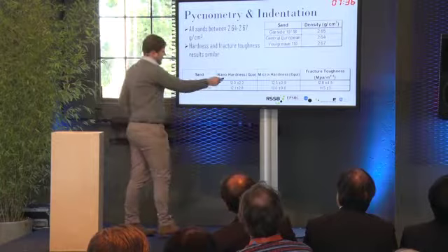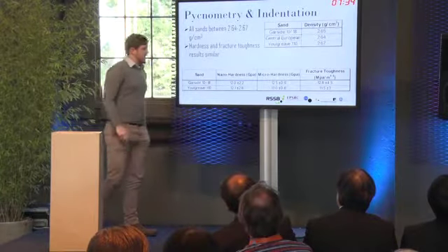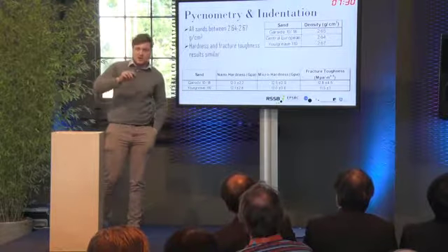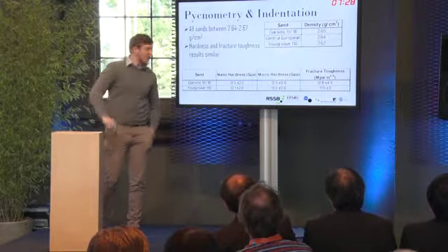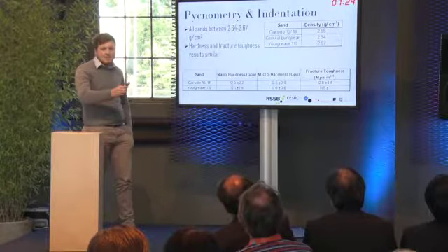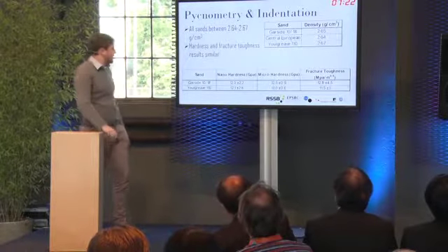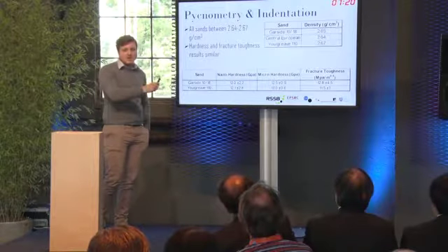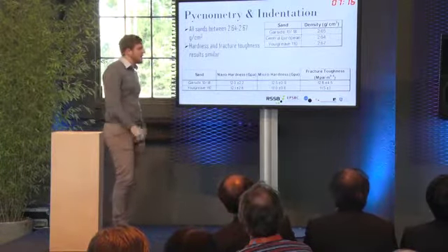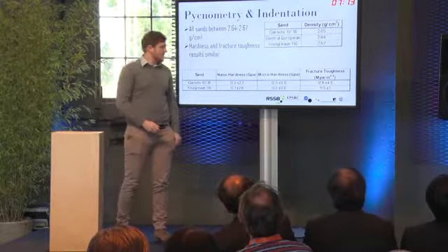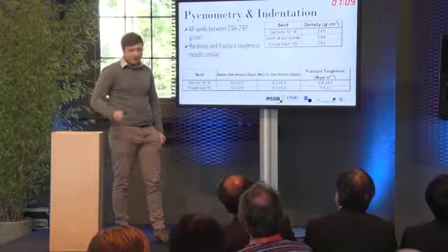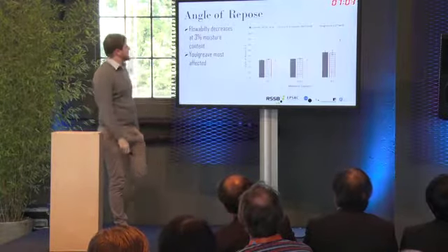There's quite a lot of variability here, especially in the nano hardness and the fracture toughness. The nano hardness is comparing local areas, so it's going to be influenced by one particular area maybe having a slightly different morphology to the other, whereas the micro hardness takes it more as a whole and obviously indents a larger area. And the fracture toughness is reported to be quite inconsistent at times, so this was no surprise.